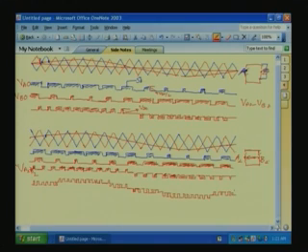So, this will have only harmonics, the 0 line is here. This will have the harmonics only at the sidebands of 4FC. So, you will get a stepped wave here. Okay. And the primary current will be more sinusoidal here. So, we will have a simulation study of this one later. But now the PWM technique we know.